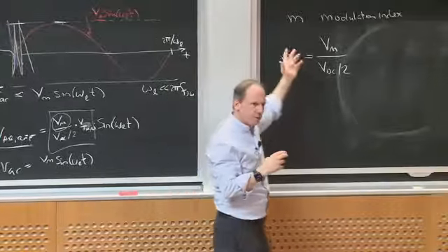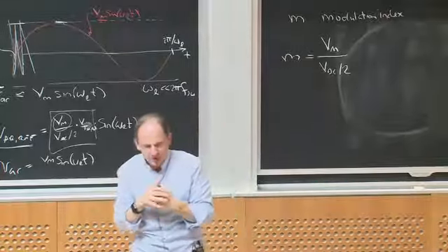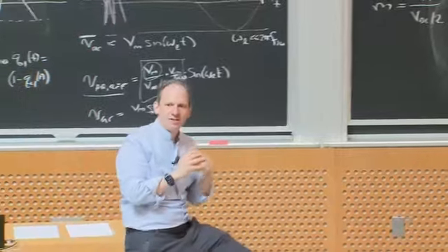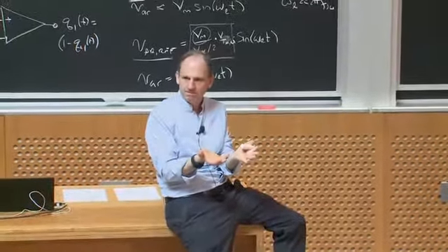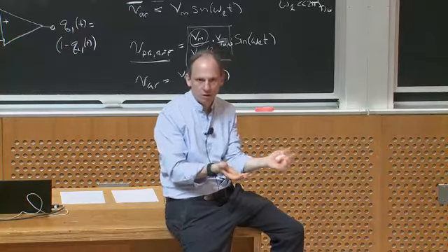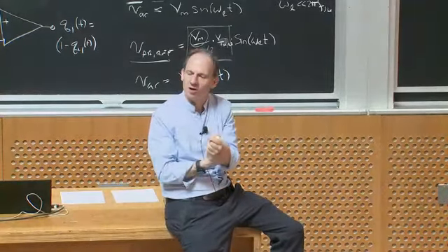Why do I think about this? Because if you think about an electric machine, and this is a typical application for this kind of thing, the back EMF tends to be proportional to speed. And how much current I want to drive in the motor, if I want more current, I try to drive more voltage, which will drive more current into the windings.